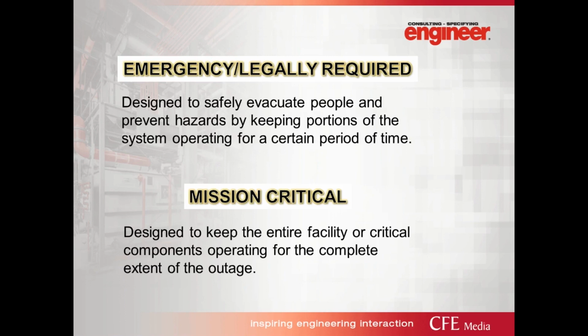So there are a couple of key differences between a typical emergency or legally required system from that of mission critical. A basic emergency system is designed to safely evacuate people and prevent hazards by keeping portions of the system operating for a certain period of time. This could be applicable to, say, a high-rise office building. Mission critical, on the other hand, is designed to keep either the entire facility or the critical components of the facility operating for the complete extent of the outage.